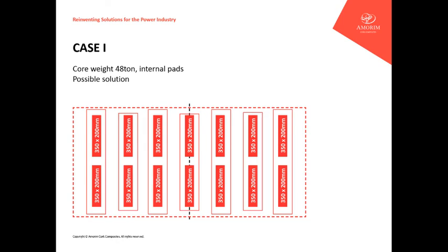Even if the legs have different sizes, we try as much as possible to design one pad size. It's easier. We don't need to remember that pad A goes to X place and pad B goes to Y place. So one size benefits the manufacturing process and the customer.